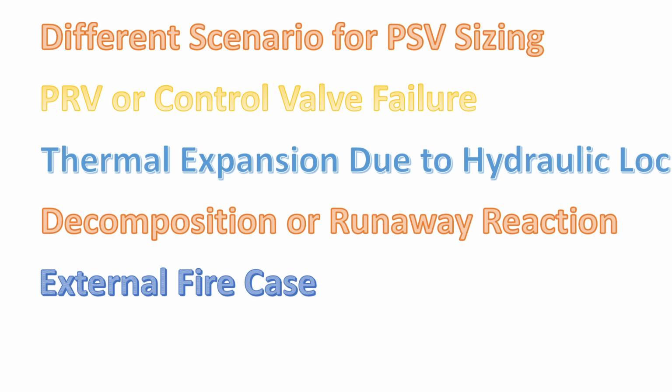And in the external fire case, the relieving rate is calculated based on the wetted surface area. And we will discuss each different scenario with an example in the upcoming series of safety valve sizing calculations.